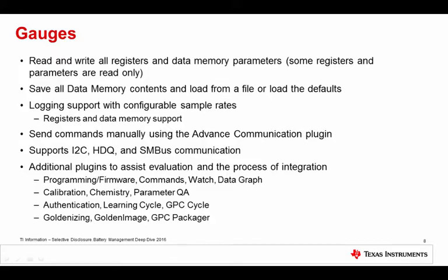There's an advanced comm plugin if you want to do low-level hardware communication. Test out a sequence of low-level commands that you might be wanting to use in a production environment. You can reproduce that with the advanced comm plugin. BQ Studio supports I2C, HDQ, and the SM bus communication. And there's additional plugins apart from just basic low-level functionality to assist you in the process of integration.